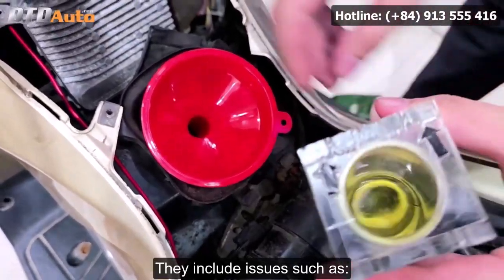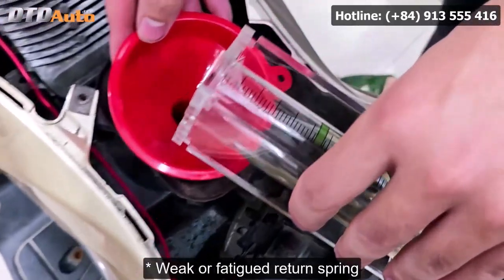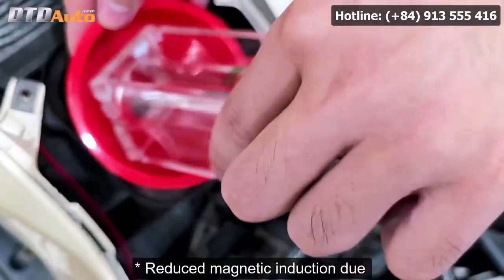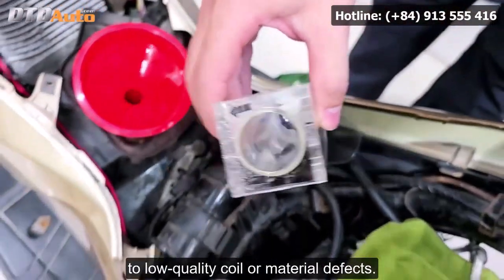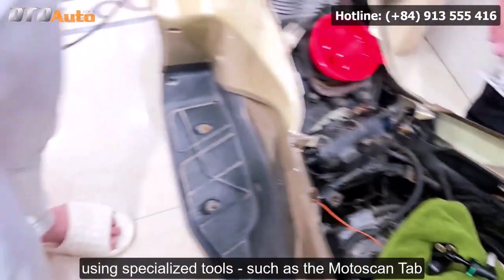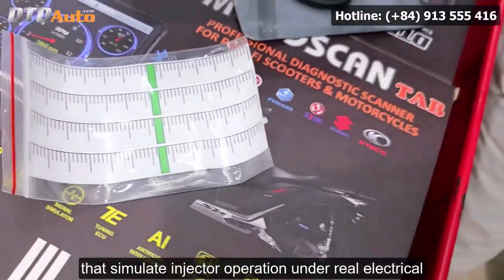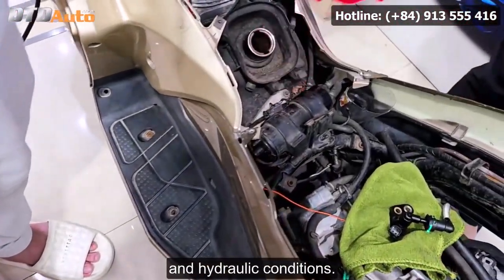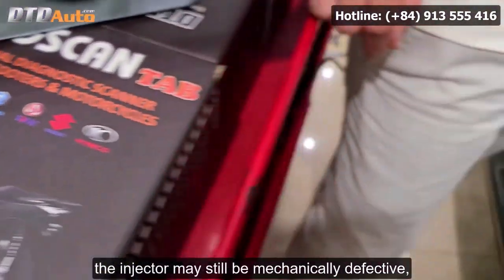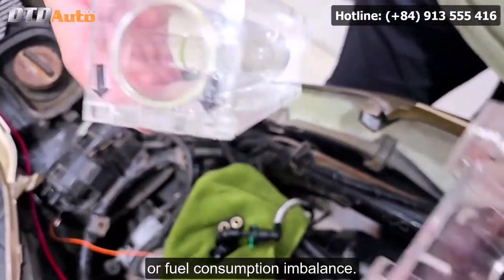They include issues such as sticky or slow-moving injector needle, weak or fatigued return spring, worn internal components, reduced magnetic induction due to low-quality coil or material defects. Mechanical faults can only be detected using specialized tools, such as the MOTOSCAN tab, that simulate injector operation under real electrical and hydraulic conditions. Even if no error code appears on the ECU, the injector may still be mechanically defective, causing unstable idling, misfire, or fuel consumption imbalance.